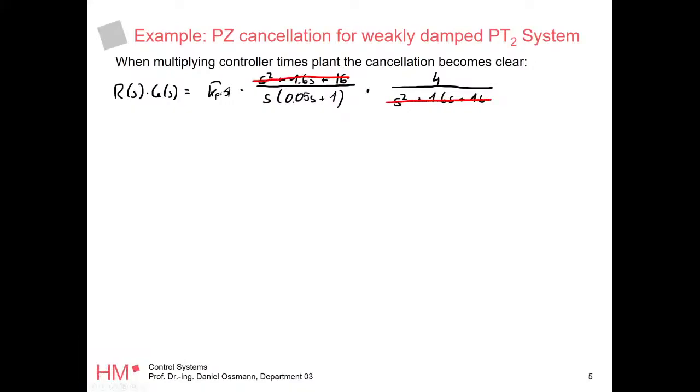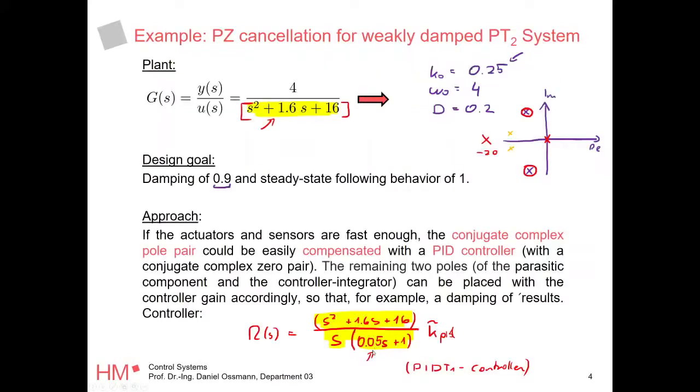So the question is, how did you choose the pole for the delay? I guess that means for the PID control. How did I choose the pole? I chose it far away from this guy here, right? So this pole here is about at 5, so I multiplied this by 4, right? So you should kind of put this pole far to the left of your system dynamics. It doesn't matter. You can set it to 0.01, 0.1 would probably also work.